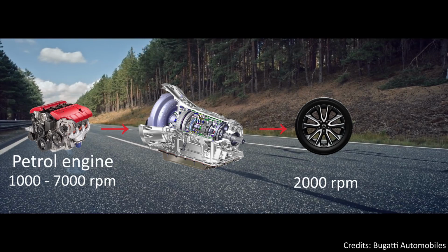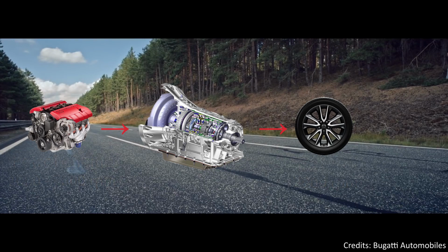Okay, you are starting to understand why a transmission system is needed, but we didn't say where it's mounted and how it works. The transmission usually is connected to the engine crankshaft through a clutch or a flywheel. The output of the transmission is transmitted thanks to the drive shaft to one or more differentials, which drive the wheels. The differential's purpose is to permit the wheels to rotate at different speeds, in order to avoid wheel spinning during cornering.